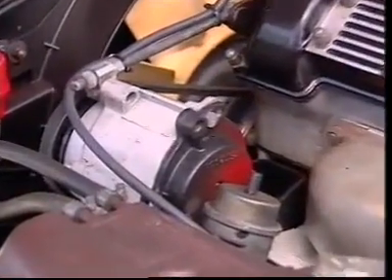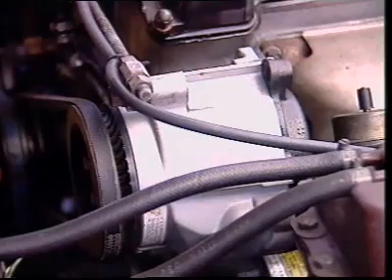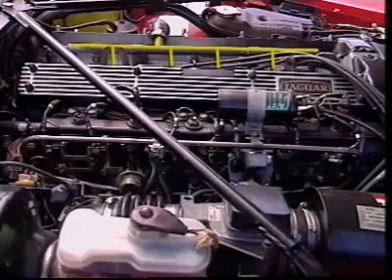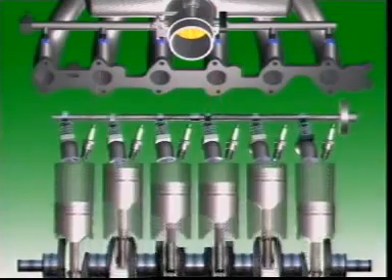Larger capacity engines may use an air pump to supply a larger volume of air. The pump is normally driven by a V-belt from the engine crankshaft and forces air into the exhaust ports. Some of the engine's output is used in driving the pump.